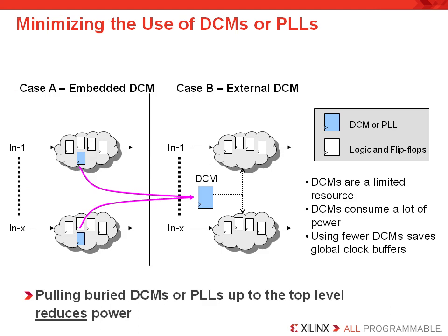Be careful when you are migrating designs to a different architecture or merging designs into one device. In this case, the design had an embedded DCM in a lower level block, and if the designer did not evaluate their design, they would now have two instances of the same block. In every design, the DCM and PLL power consumption is considerable, so this can really add up. So pull those DCMs and PLLs out of the top level of your design hierarchy so they are not replicated by your synthesis tool.